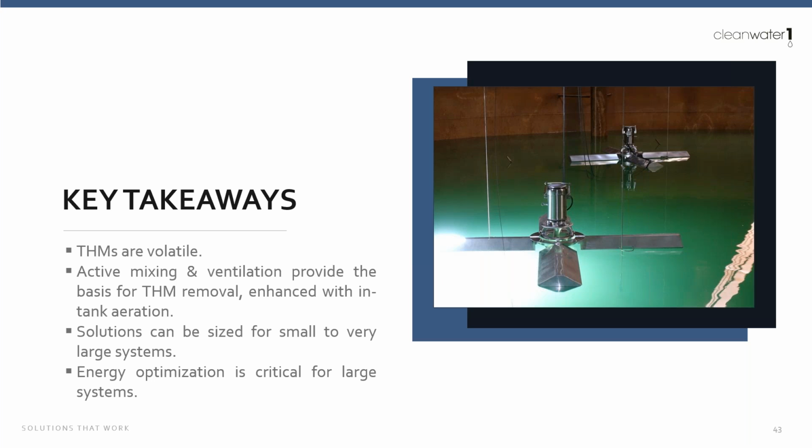But also remember, if you need to get back into compliance and you're under the gun, THM aeration is a really well understood and well established treatment technology at this point. We've done hundreds and hundreds of installations. We have a high level of confidence about what level of removals we can achieve. We've got process guarantees. And we've got this great technology, active mixing plus headspace ventilation alone. It's cheap, it's easy, and boy, can it fix a lot of problems.